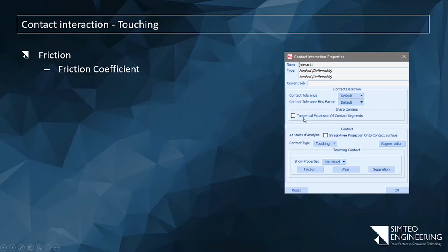Okay, so to do the first, you activate that tick box. To do the second, you activate this one. The first one you use whenever you have a block standing on top of a block, so edges that are really close together, and you're not certain whether it may fall off during the run. The second one is for when something initially should make contact but not have a stress; you can activate that section.